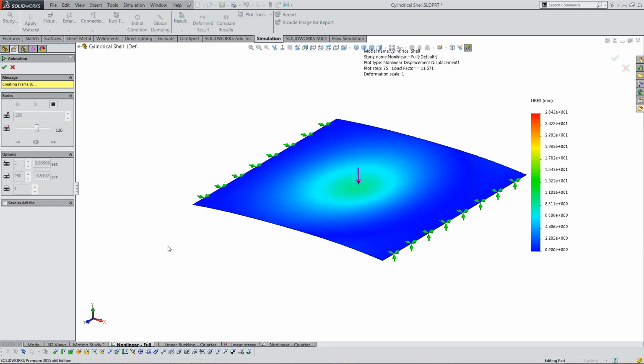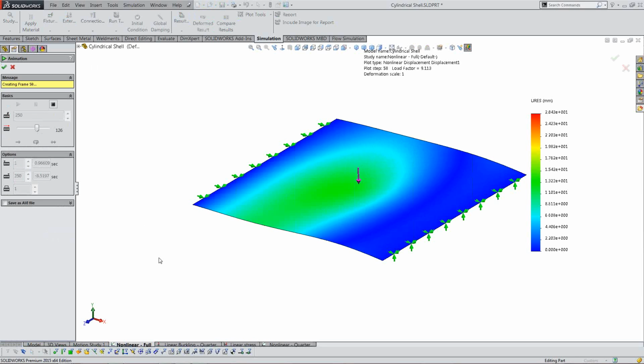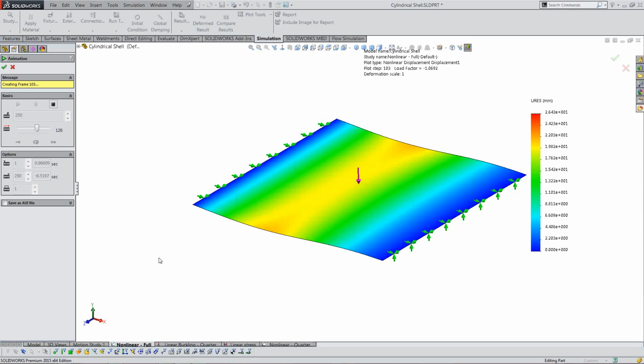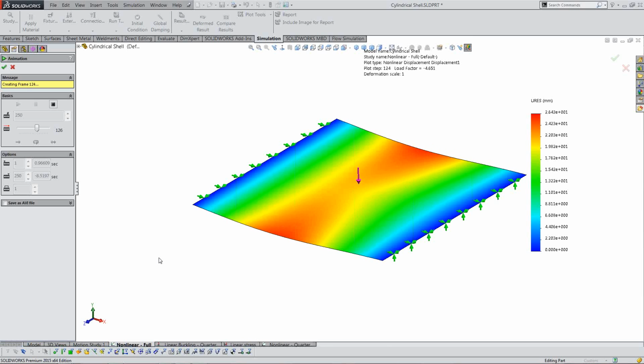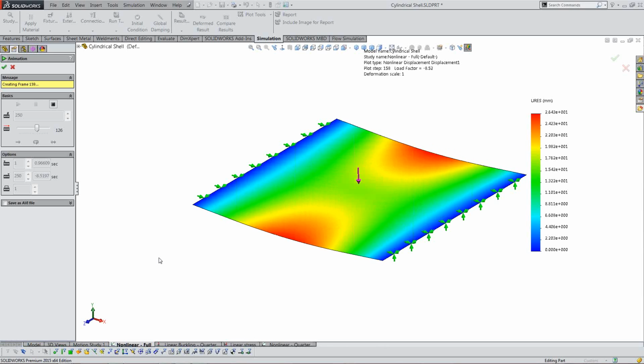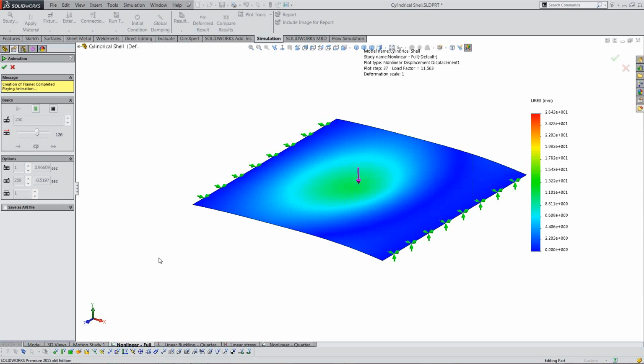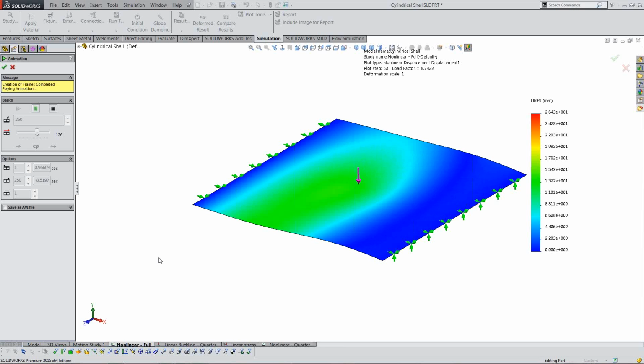This is kind of interesting. So you see, and I'll replay this, the green area is the part that's displacing the most, right? And then the yellow and red. So initially, the deformation occurs at the center of the sheet where the load is. And then you see it become unstable and wobble off from one side to the other. And it's biased towards the side where the load is. So the green is now progressing to the left.